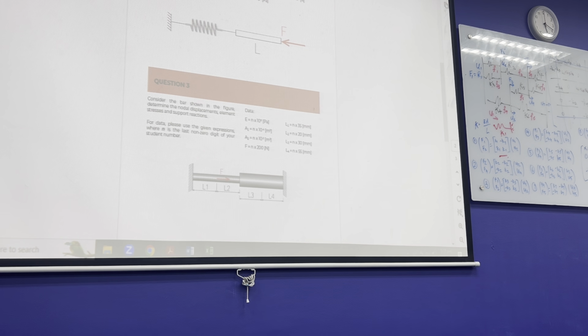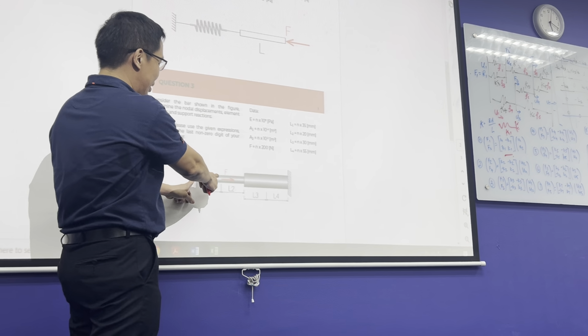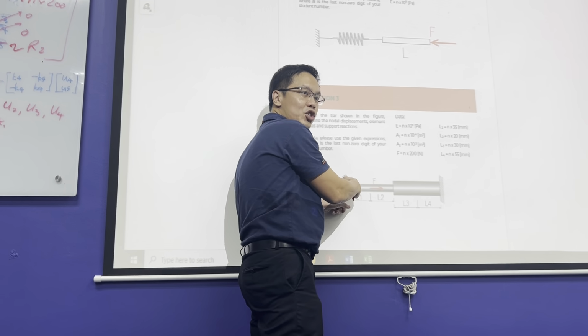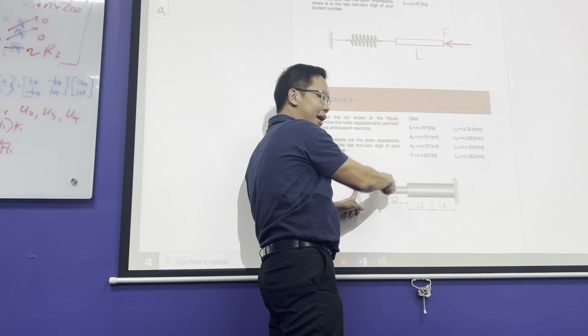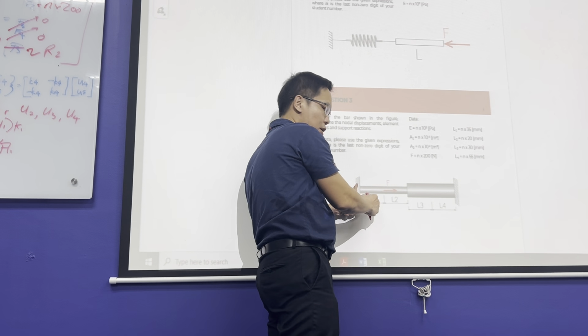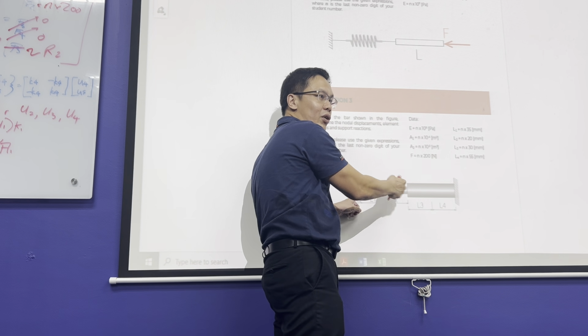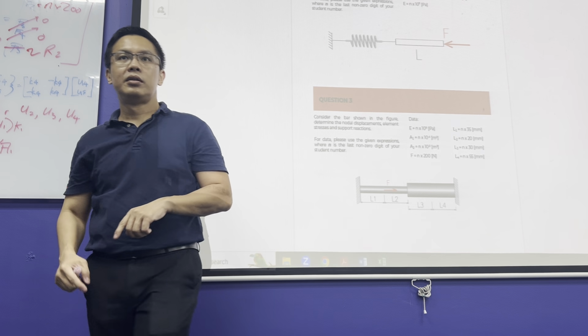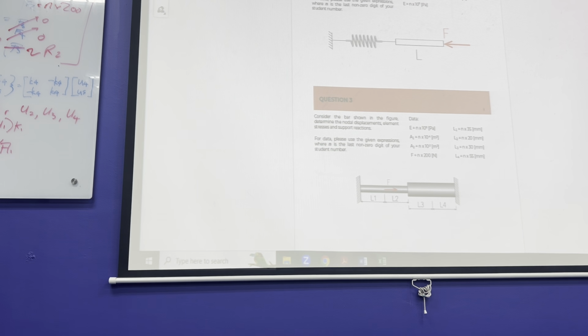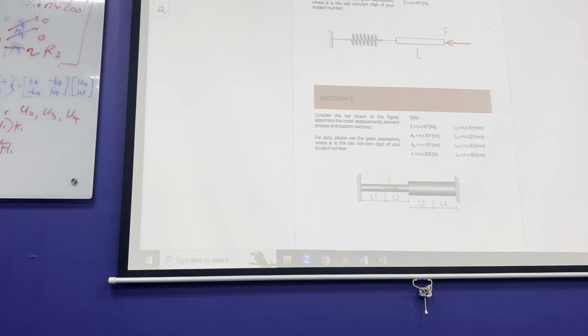So what you will do is you find the same thing as what we have here. I have my displacement here, assuming this is fixed, correct? I do it back here. The displacement of this, U2 minus U1, that's okay, will be your reaction force. So it's R1 equals K1 (U1 minus U2). Correct.